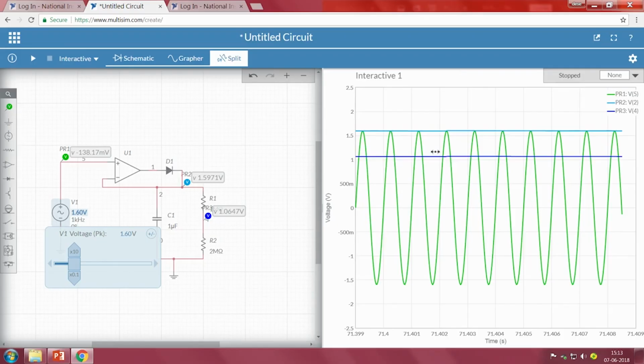A simple comparator is enough. We do not have to go with any Schmitt triggers or anything. The reason is we are not setting any two thresholds here, we are using only a single threshold. If the input value is greater than this particular value, only that signal has to be passed, detected, and counted. Depending upon how many such pulses we are getting, if you use a counter there, then we can automatically see the number of pulses we are getting per second or per minute.